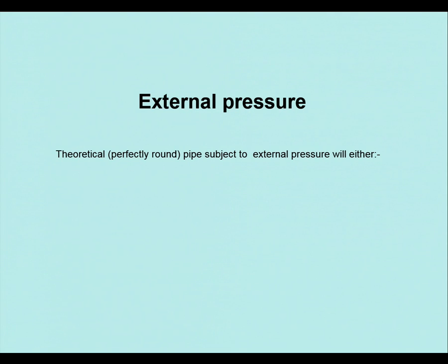If I've got a pipeline and I've got external pressure, theoretically the pressure on the top of the pipeline is slightly less than the pressure at the bottom, but we take the pressure at the bottom because the difference is so small it doesn't make any difference. But that pressure acts all the way around.